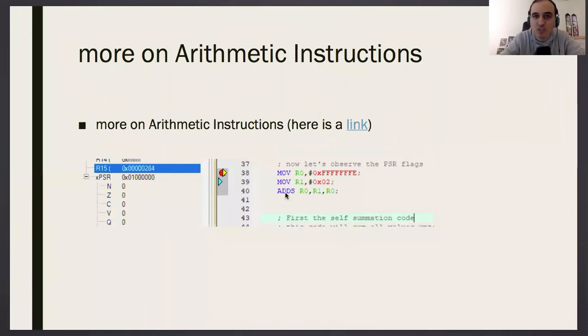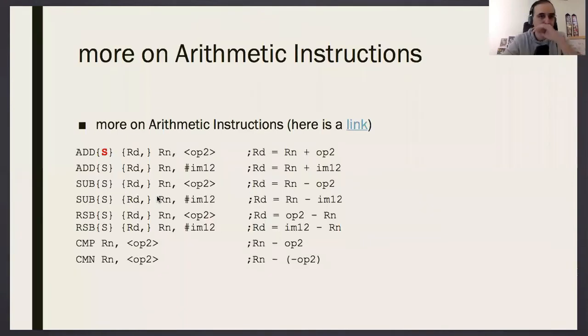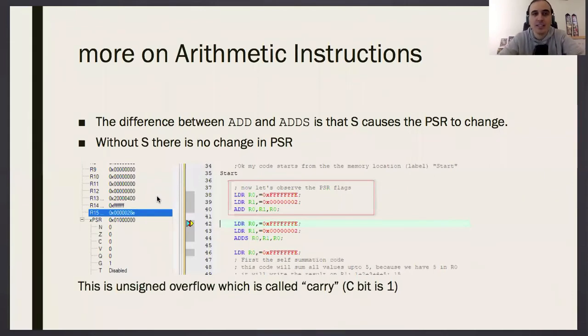And actually, when you do this move, there are other registers here. You are going to see them. So line by line in Keil, you can debug them. And this Monday, your teaching assistant will show you how to do this. Okay? So this is a demonstration of how you test your code and see the registers and see the flags. This is XPSR, the flags. So on the left-hand side of your screen in Keil, you in real time see what register values you get or what flag values you get. Okay?